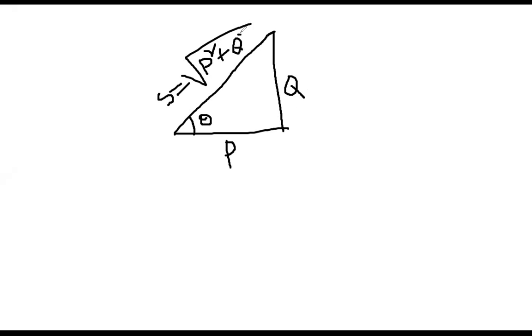Now, for example, we have a certain value of Q, and the P equal to that 20 kilowatt. The problem says this is fixed. So when this is the value of theta and this is the value of Q, at that time this is the P. Now with the same P, for example, you inserted a capacitor. Because you inserted a capacitor, this Q magnitude got reduced. For example, your new Q magnitude is this.